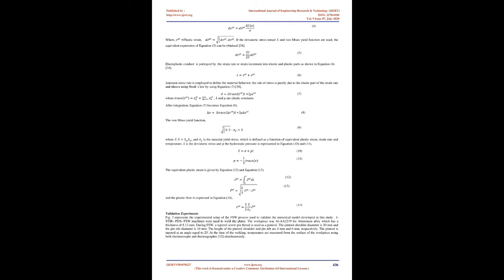A CFD model was developed by Zhang et al. 28 to research the spatial dispersion of frictional heat flux and plastic deformation during the FSW of AA2024-T4. In their work, the distribution of frictional heat flux at the welding tool/workpiece interface is represented using a Gaussian heat source model.